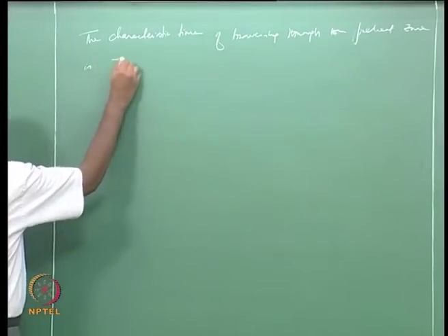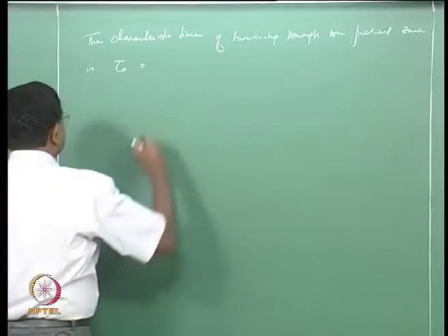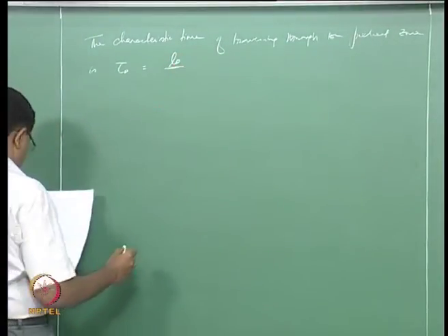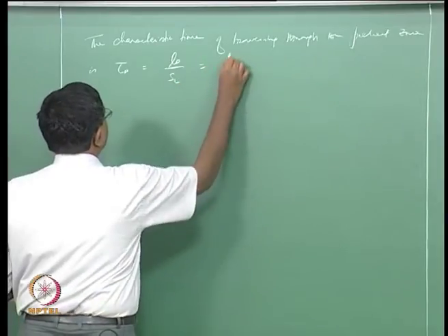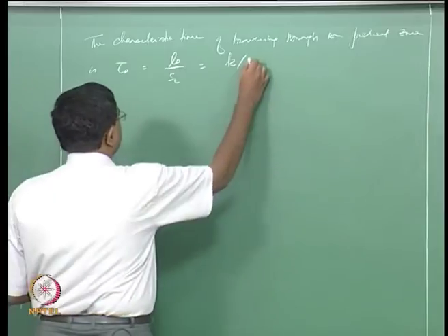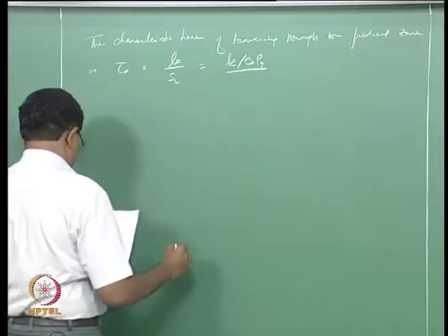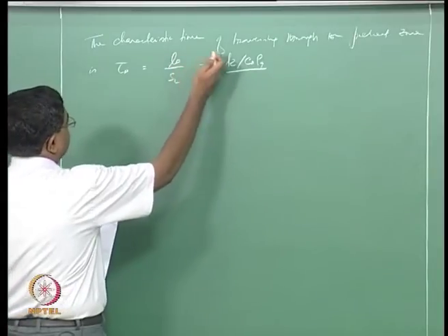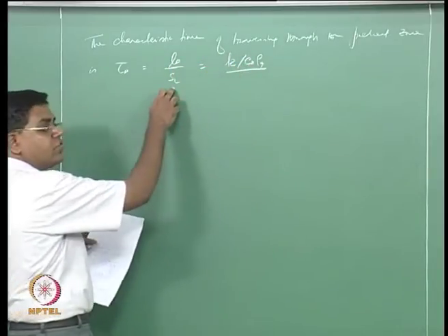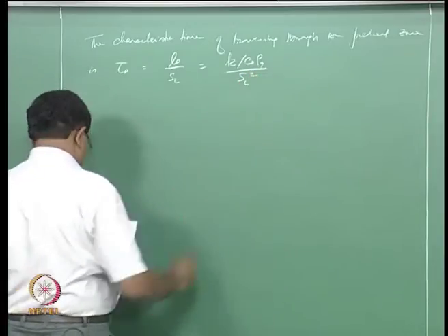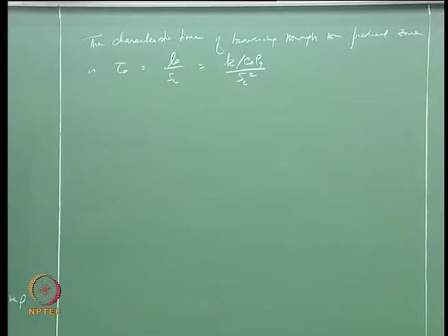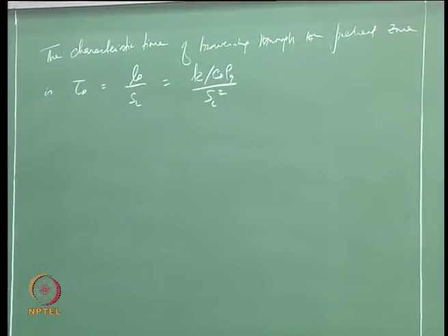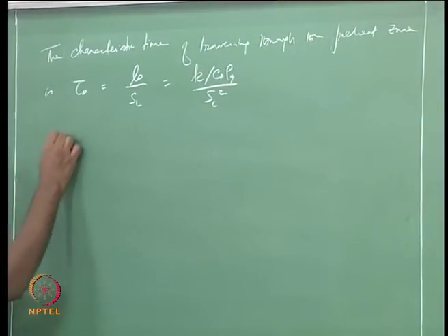is, let's say, tau d equals LD, which is like the flame thickness divided by SL, and that would be K divided by Cp rho g, divided by SL. We actually have LD as K divided by Cp rho g SL, then we also have another SL, therefore you get SL squared. Then what we have to compare this time with is the droplet evaporation time. How long does it take for the droplet to evaporate versus how long is it going to be within the preheat zone, right? So the droplet vaporization time